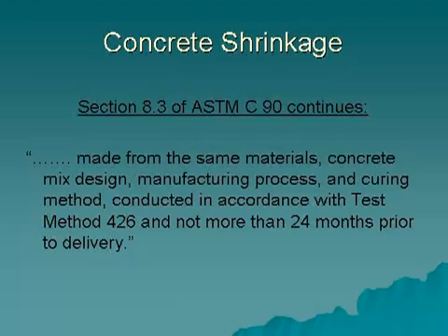Interestingly, the publication, Inspection and Testing of Concrete Masonry Construction by the National Concrete Masonry Association and the International Code Council states in its commentary on ASTM C426 that the test procedures are extremely sensitive to user error. Even minuscule deviations from the intended provisions of the standard or errors conducting the test can have a dramatic impact on the measured results. Therefore, only qualified laboratories should be used to perform this test.